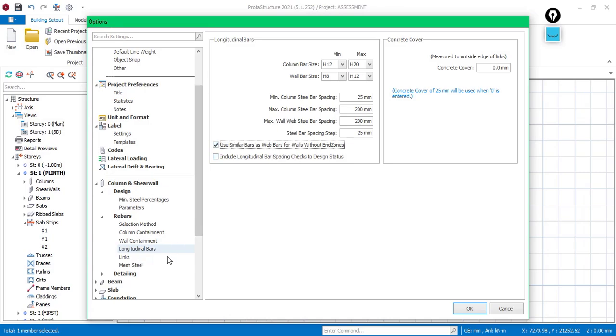And then the concrete cover to use, we have exposure conditions due to fire resistance and humidity, environmental conditions that will enable us give us the concrete cover. But in this case, if we do not choose the concrete cover, the software will only give us the 25 millimeters. If we choose 0, the software will make for us 25 millimeters.